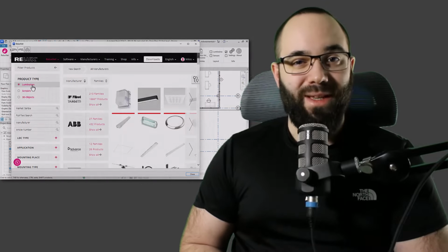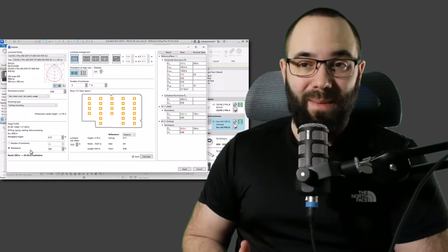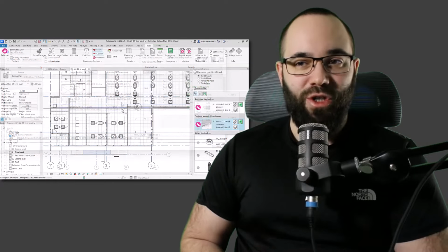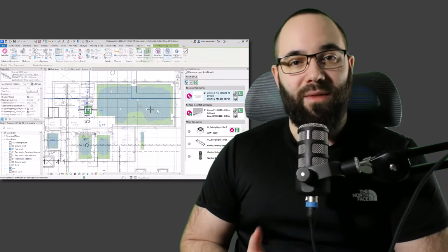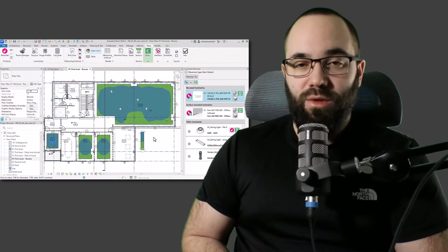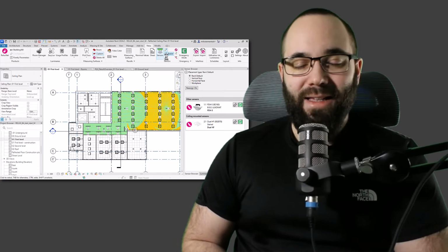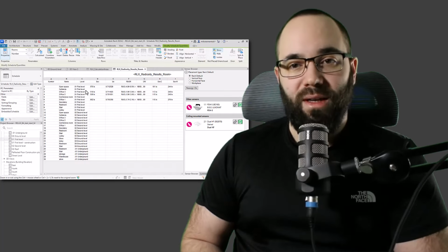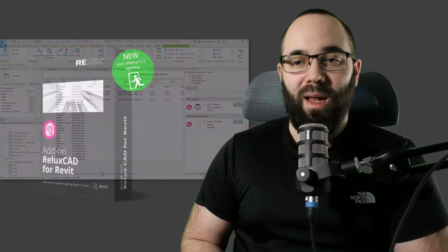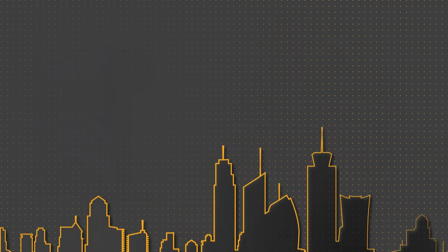In this video, we will be searching for light families, loading them into Revit, placing them automatically, setting up emergency lights, setting up standards, and then checking if we have achieved those standards. We're also going to be finding some sensors, placing them, analyzing the coverage, and finally generating schedules for everything. All of this will be done with the help of ReluxCAD Add-on for Revit. Let's go.